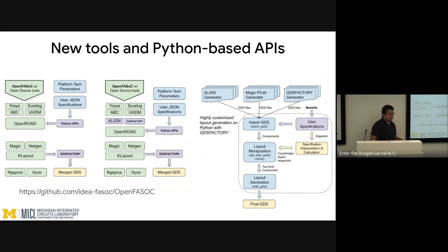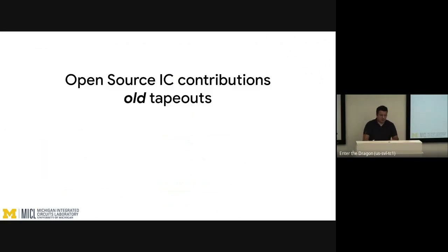So we started making these Python APIs that basically create polygons, that create for you test structures that are useful for your design. So I'll go in more details, but that basically evolved our flow into more than just using a cell-based approach, but using also a customized layout, which is really required for some of the analog blocks if you're used to analog design. So anyway, I'll move now to the tape outs.